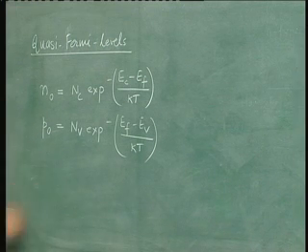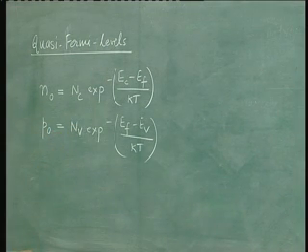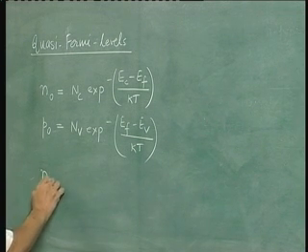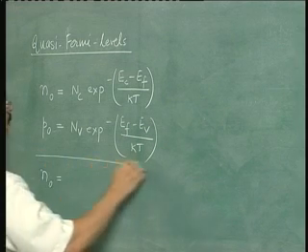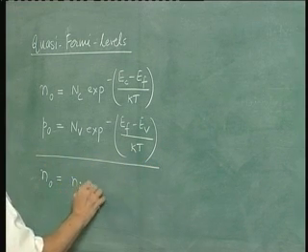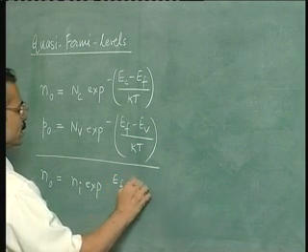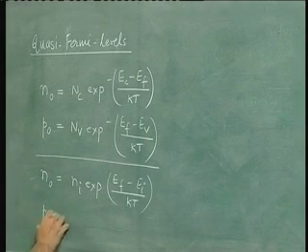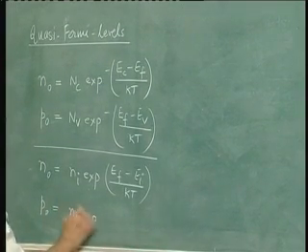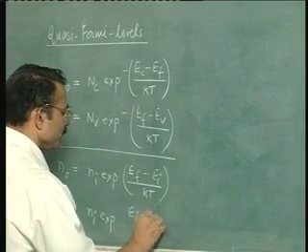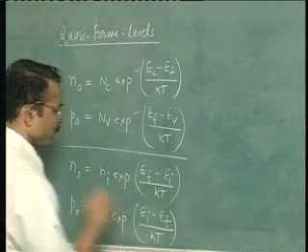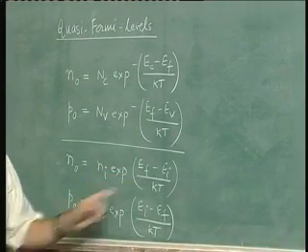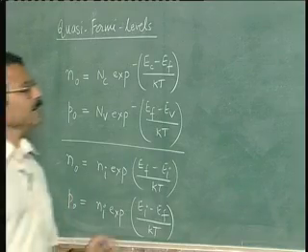You can also write the electron and hole concentrations in terms of the deviation from the intrinsic semiconductor. So, for example, I could write N0 is equal to Ni exponential of (Ef minus Ei) upon kT, and P0 is equal to Ni exponential of (Ei minus Ef) upon kT. This is another way of writing the same concentration. Now, here the Fermi level is again the same that is used in both formulae, and the diagram is as follows: